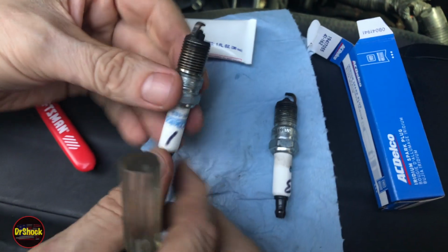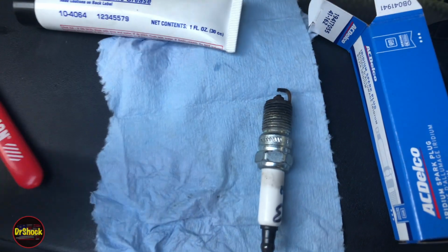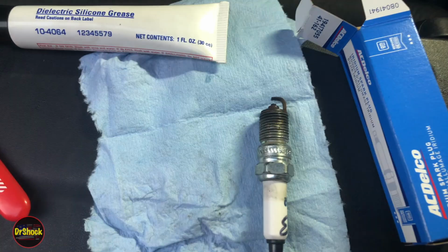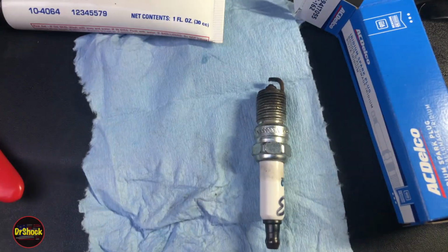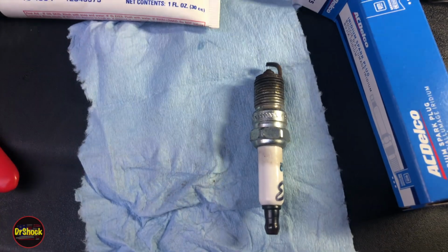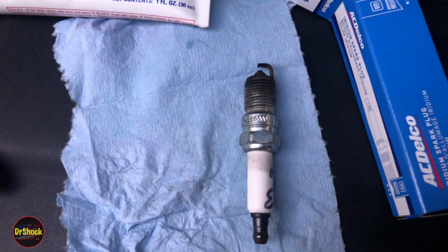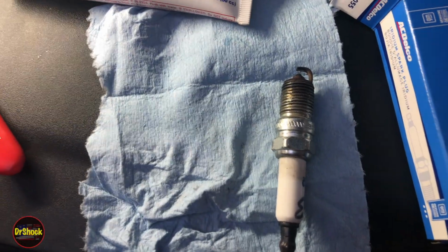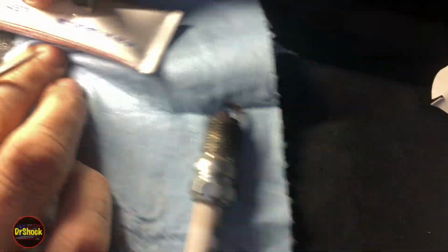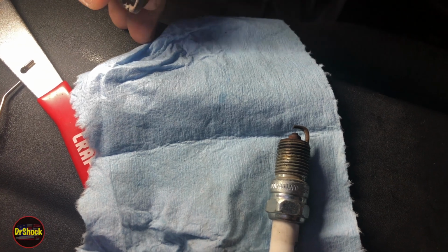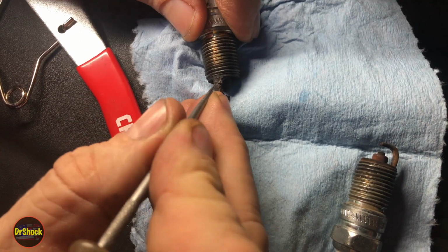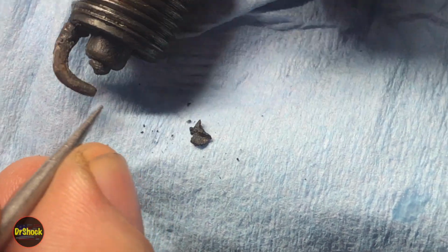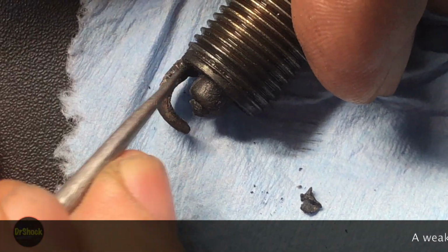The last thing I'll show you is, if we take a close look here, let me see if I can get over here where the flashlight can sit and help us. The problem with these modern trucks is trying to find something made of ferrous metal, so you can actually get magnets to work. So what we saw on here is all this carbon buildup, right? And chip all that off. That's what you're getting from the oil burning.